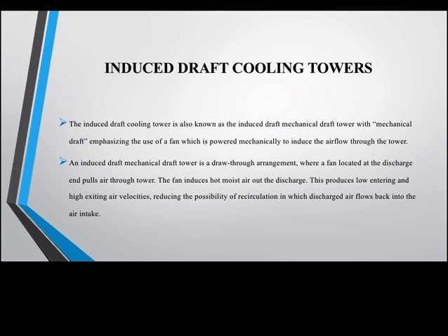This type of cooling tower has its fans at the top, and these fans are powered mechanically and induce the airflow through the tower. So these fans at the top of the towers pull the airflow through the tower out to the atmosphere.